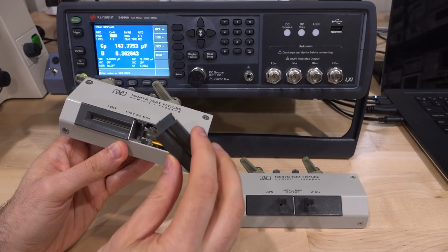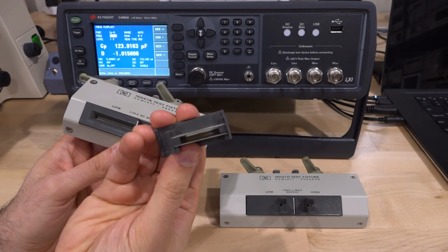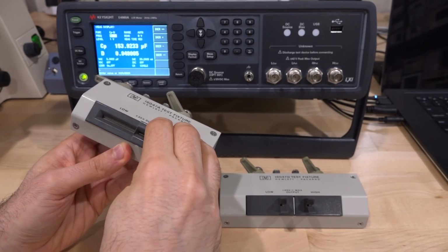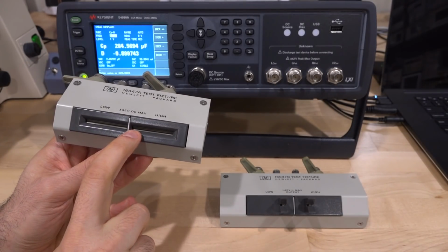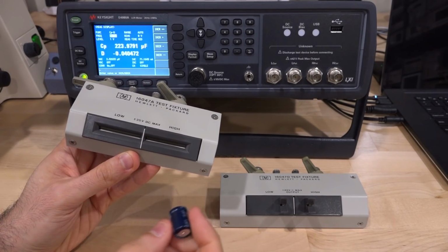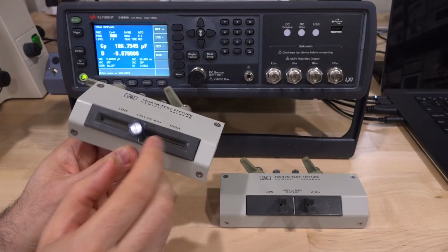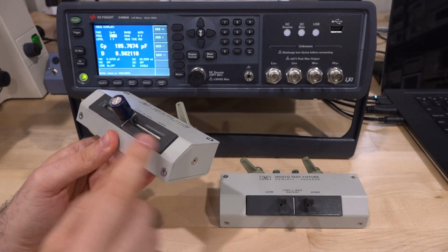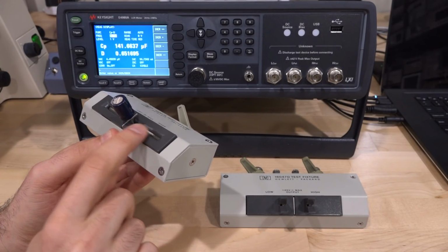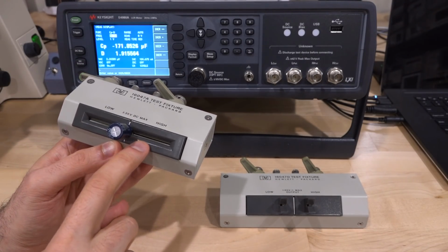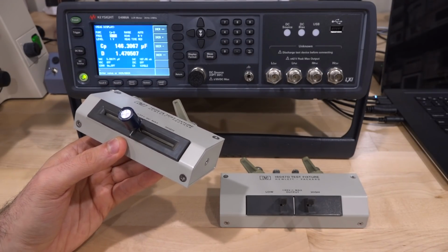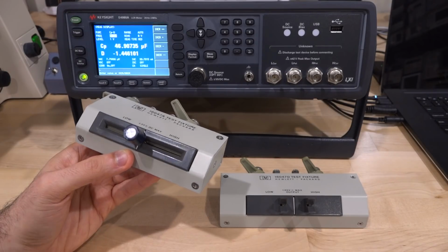So even when you place this inside, there's two plates in here that are free to move, and they're not touching each other either. So when you squeeze this in the middle, now those two plates have a little gap in between them. They're not actually in contact. And as soon as you push something in the middle of it, then that pin is the only point where the center pins of these two begin to touch each other, right where that pin is entered between the two plates. And look how clever it is, and you can see the rest of it is open. So that's how it brings that connection as close as possible to the device under test,